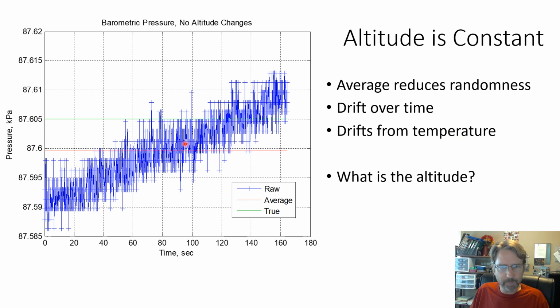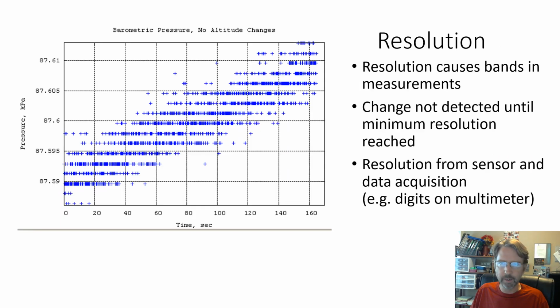All right, so you have a bunch of data and you average it and hope that you've got good data. And so you test it out with calibration plots to make sure it's working. I think the last thing here is looking at resolution as one of the terms. Resolution is the smallest change that you can measure, and you can see it here by not connecting the measurements. These are really going up and down.